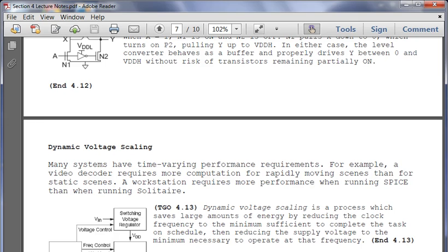Particularly in pipelining, you put your output result onto the registers, right? So if you're doing it for an adder, you can slow down the time it takes to do the adder. And once you put the result on the registers, just turn off the ALU. You're not using it, so you reduce power. Because if you have it on, you're going to consume the same amount of power for multiplication as an addition. So you can use this dynamic voltage scaling: if you know the particular operation you're doing at any given moment, you can significantly reduce that power, and still meet the performance constraints set forth by the customer. I should add that.